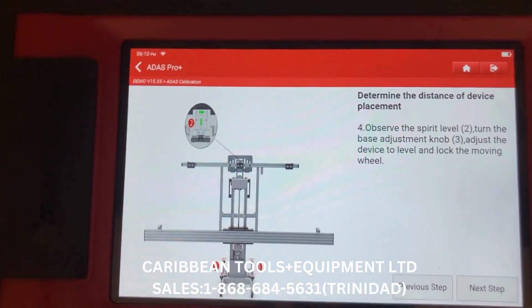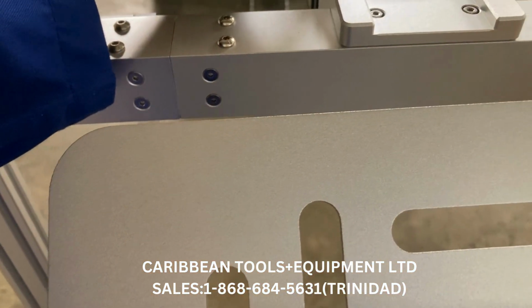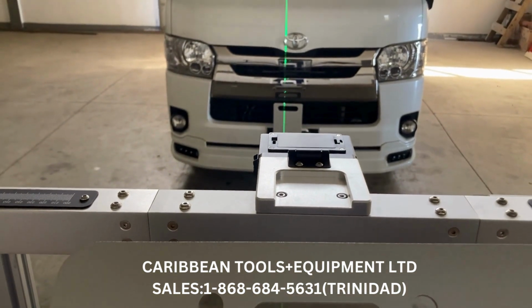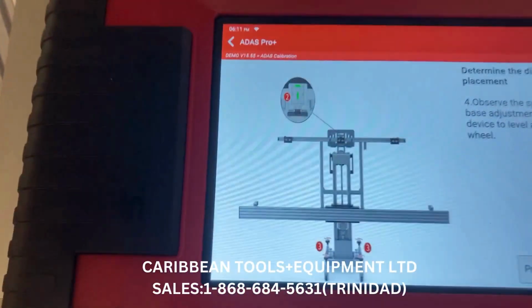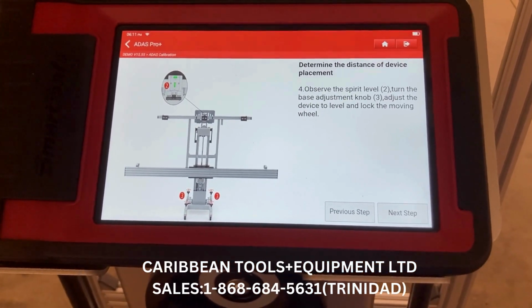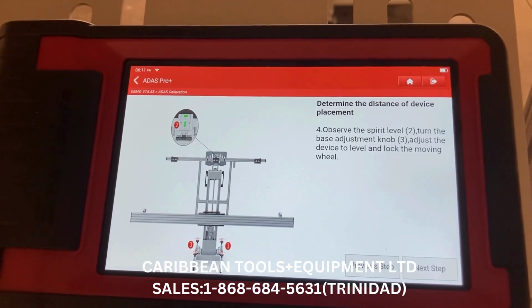We need to turn on the center level to center the vehicle to the frame. So that's this one here. With that laser, we should be able to center the frame to the vehicle. So we're going to go ahead now and adjust the frame to the center of the vehicle.